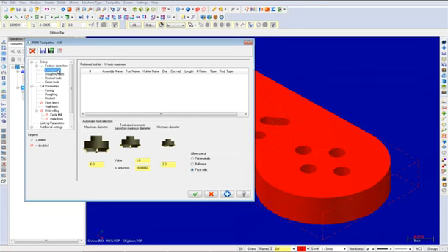Automatic tool selection applies only when tool selection options use tool library or create as needed are selected in the setup page. Maximum diameter enters the maximum tool diameter for automatic tool library selection or tool creation. Minimum diameter enters the minimum tool diameter for automatic tool library selection or tool creation. Tool size increments based on maximum diameter defines the size gap between tools that Mastercam uses to find or create the next available tool size. And finally, allow use of selects the tool type Mastercam should choose or create for the operation type.